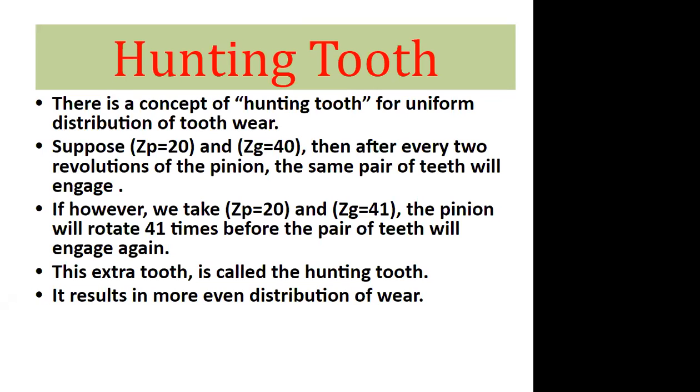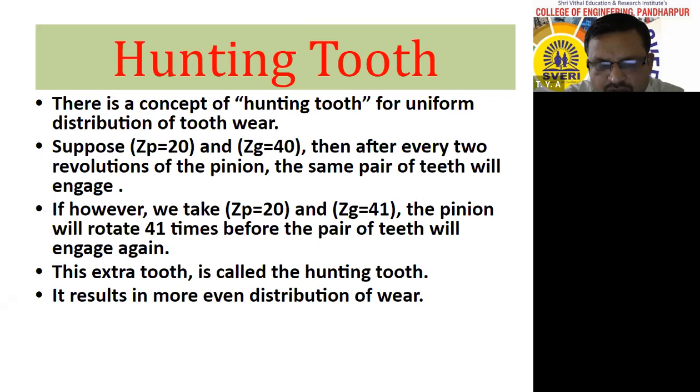Therefore, what will happen? For every 2 revolutions of the pinion, the same pair of teeth will come in contact with each other. Every time that same pair of teeth comes in contact, there are chances of wear and tear of those two gear teeth.